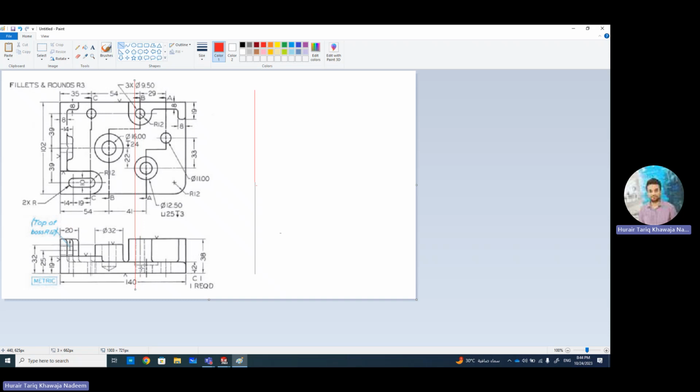You can see that the center line and the hidden line are coincident, but they are overlapping. The center line of the top circle and this hidden line are overlapping. So that's why you have to take care of this. Now this is the center line of this counterbore. And there is this hidden line, which is over here because of this edge. This is the edge of the hidden line of the counterbore. So let's make a counterbore first of all. We'll come back to this place.